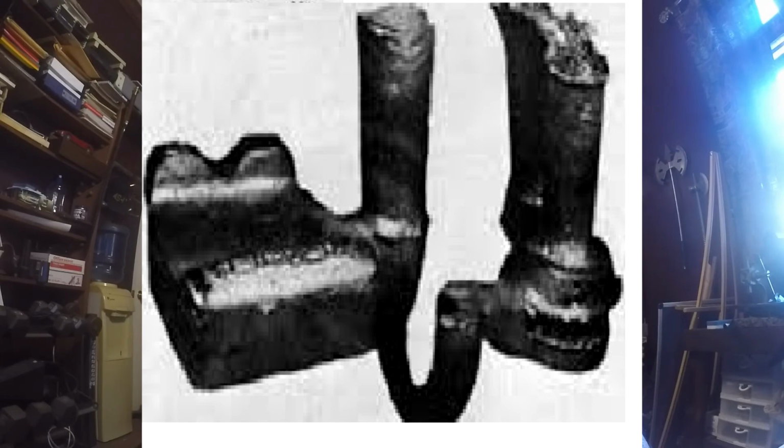But once it became poured and that area started to fill up, it ran into the horn gate. The horn gate directed it to the bottom of the riser and fed the mold cavity, filled up the mold cavity, and then once the mold cavity was full, the way the horn gate was pointed towards the riser, it would fill the riser last, giving you the hottest metal in the riser to feed that casting.